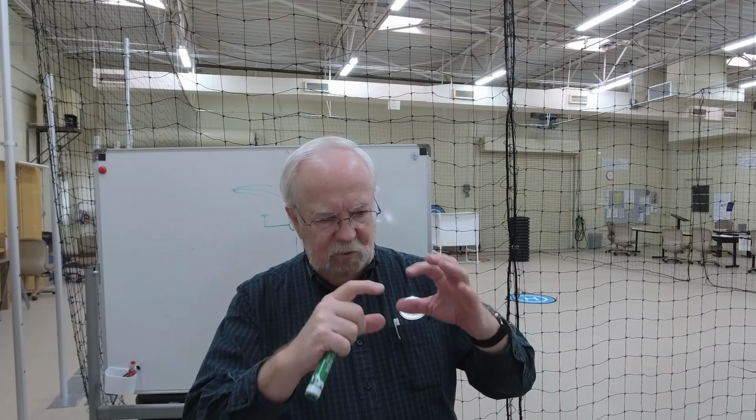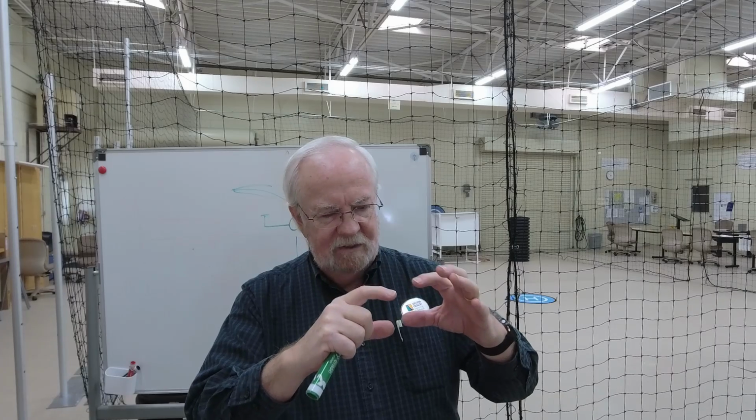Another question: how can a remote pilot determine the altitude of the terrain and structures where the flight will be conducted? Obviously on the sectional chart. That's why we studied that. And there'll be a bunch of questions on that as well in a separate section. But yeah, the sectional chart has the heights of the towers. A tower has a bold number, which is the mean sea level altitude, and then has brackets with a smaller, not bold number, which tells the height above ground level, which is what we care about as drone pilots.